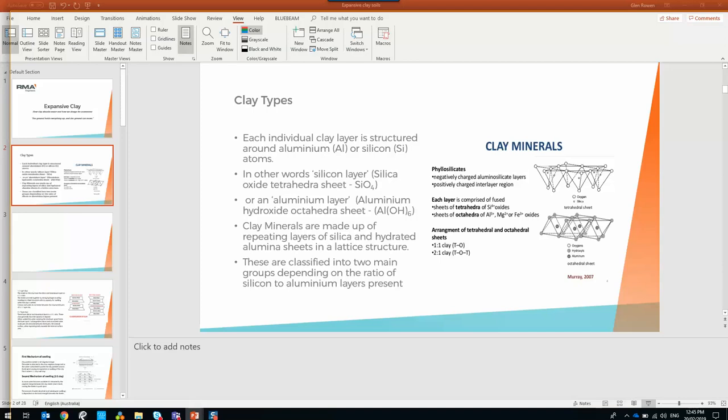Here's a typical section. If you look up in the top left, that's the typical perimeter detail. That one there had some specific things. We normally wouldn't suspend the slab edge over the thing, but there was a specific detail the architect wanted there. So that is what it looks like when it's getting prepped. You can see the void former poking out there, and that's what it looks like when it's finished. So they get a join there, and it looks quite neat.